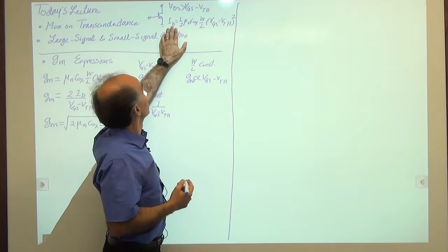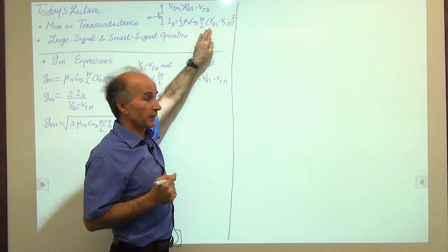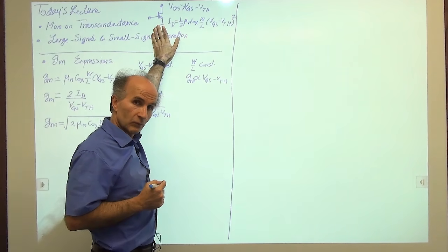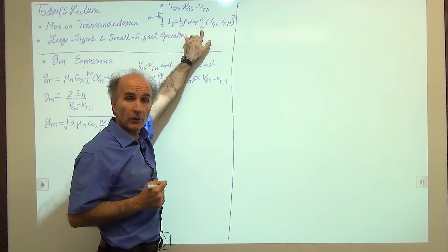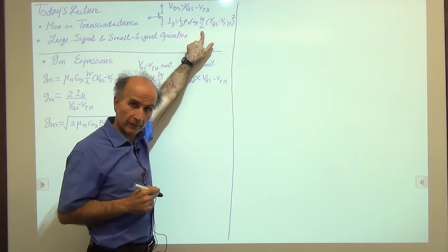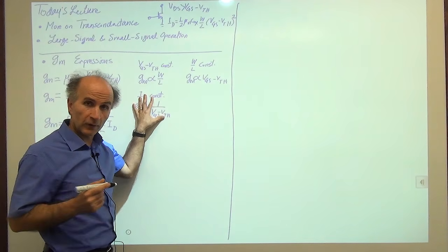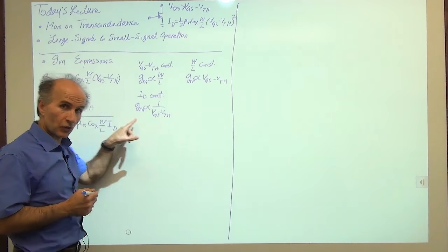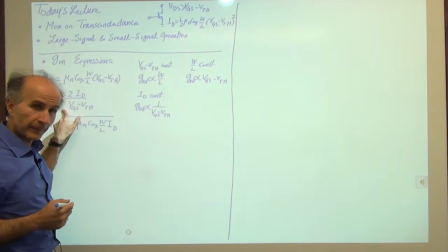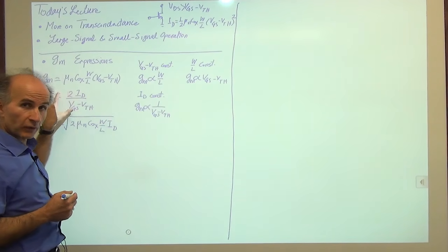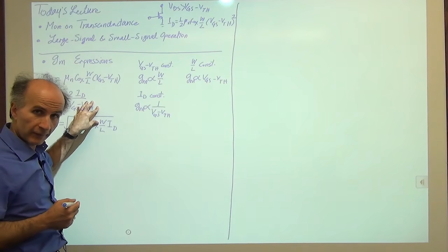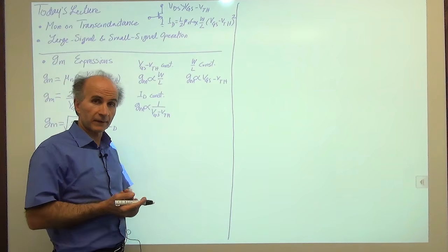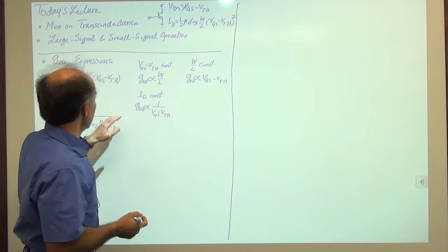Well, we go back here. Remember, there are three parameters here. So is it possible to increase VGS minus VTH while ID is constant? Yes. We have to reduce W over L. It is possible? Yes, we can do that. So this condition is possible. We just have to be careful in terms of what it means. It means that if you are changing VGS minus VTH, in this experimentation, and you'd like ID to be constant because we're trying to see the dependence of GM upon overdrive, then implicitly we're assuming that W over L is decreased. All right?